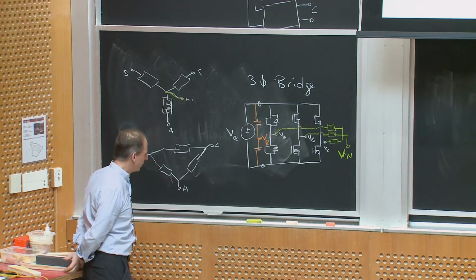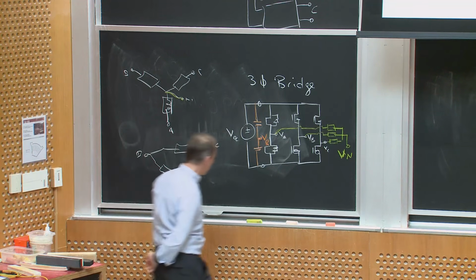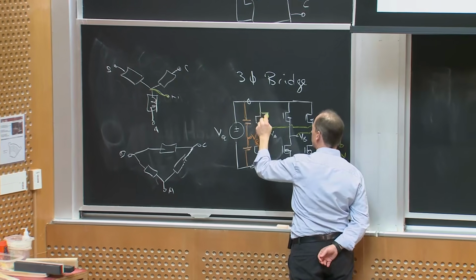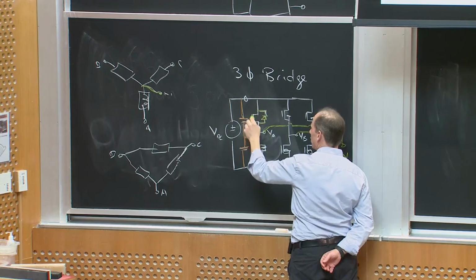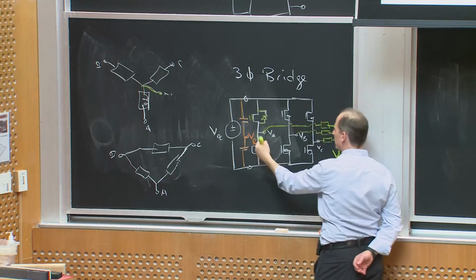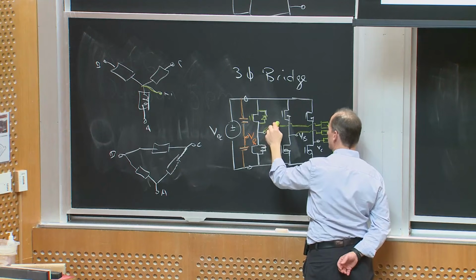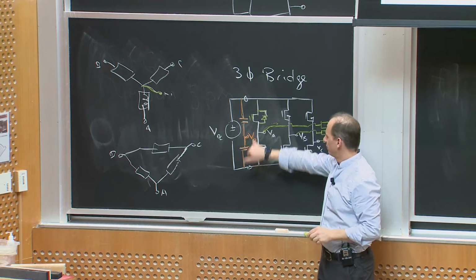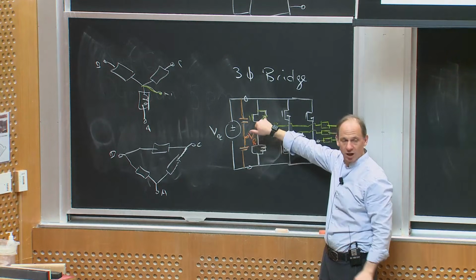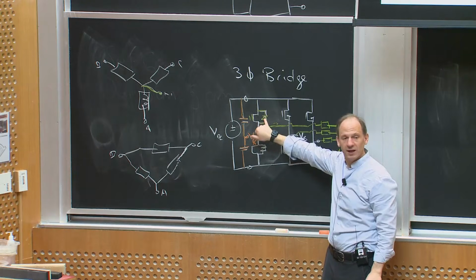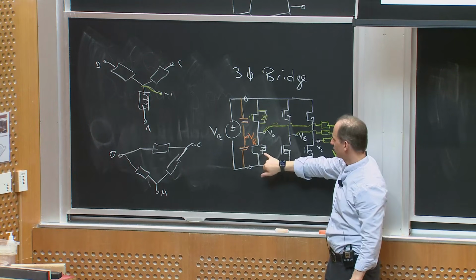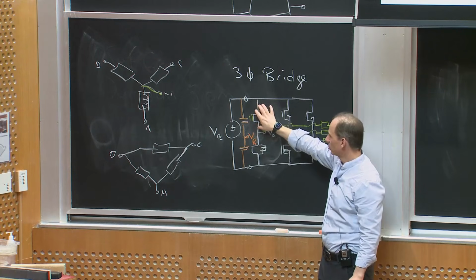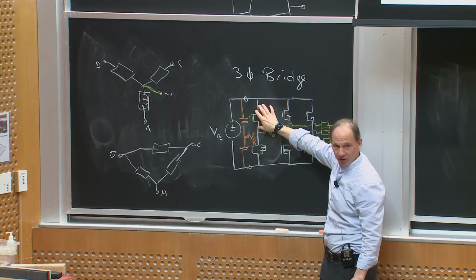Okay, so one thing I wanted to note is that I want to pay attention that these devices are, especially if the load's going to be inductive, so I don't actually control instantaneously the direction of that load. I usually have devices with reverse diodes on them, or I use MOSFETs which have it built in, because that way when I turn one device off, I can always guarantee there's a path for the current. So these are single directional blocking, bidirectional carrying switches.